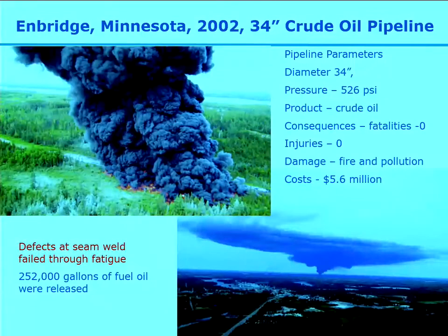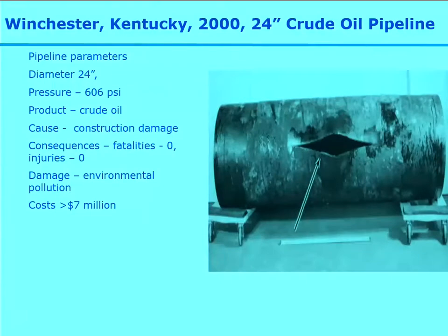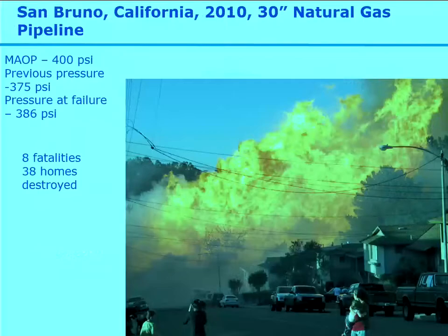I apologise for that. The issue was the pipe had been transported for hundreds of miles on a train, and therefore it had been subject to vibration on the train, and that had caused very small crack-like indications to initiate in the seam weld, and then once it was in service, they continued to grow by fatigue.